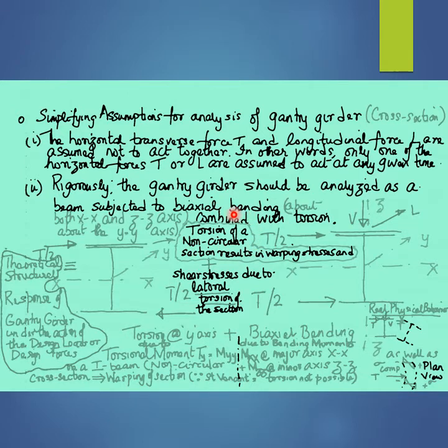Recall from your basic first year undergraduate course on solid mechanics that torsion in an element with a circular cross-section, that is a cylindrical element, results in Saint Venant's or pure torsion, while torsion in an element that is non-cylindrical or has a non-circular cross-section results in warping of the cross-section, which needs to be modeled separately.